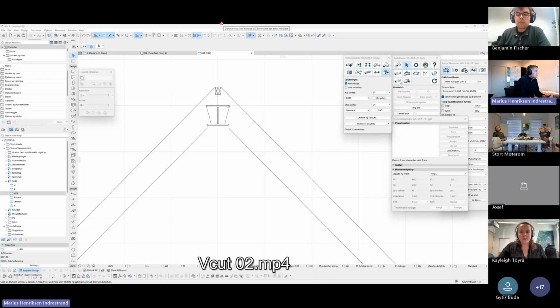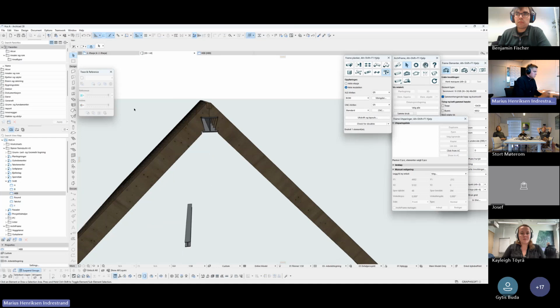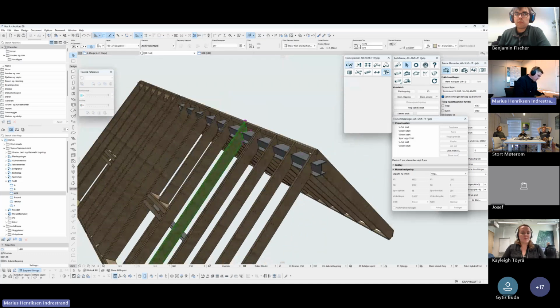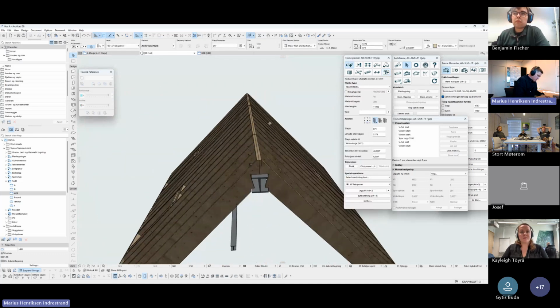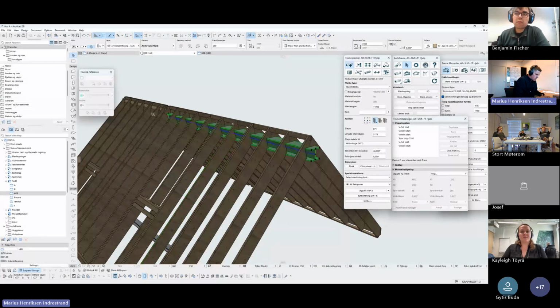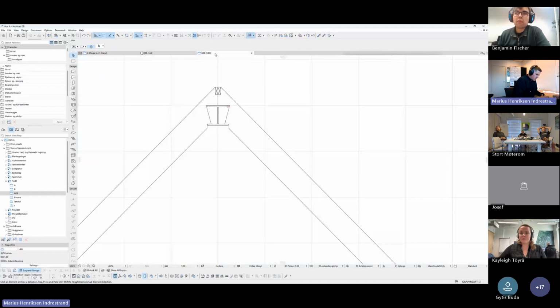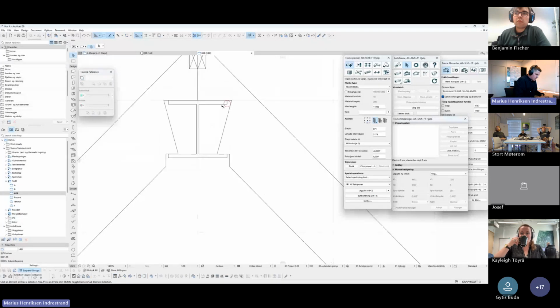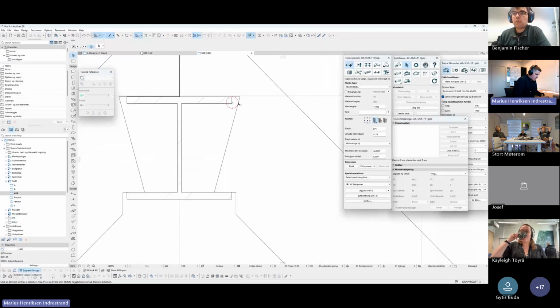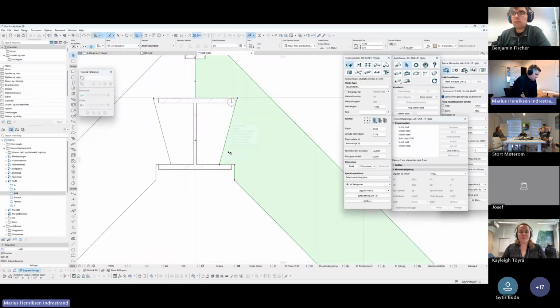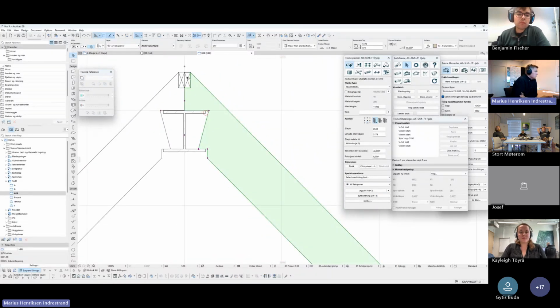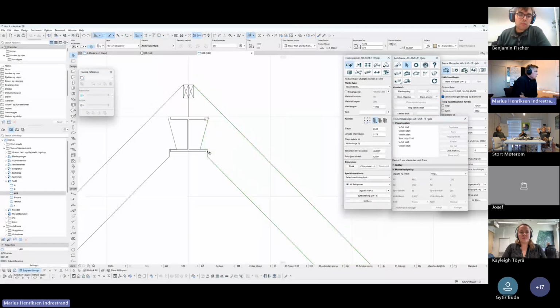Well, I have a few more examples where VCut is used or can be used. This is a project with roof elements, quite steep. I think it's 46 degrees. Steel beam and a glue laminated beam. So for HIB, I'm checking that this rounding clears the steel, and this piece is made with a groove in the top. This is a VCut, and also this is a VCut.